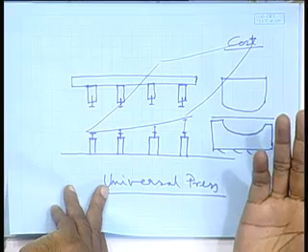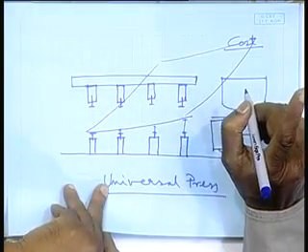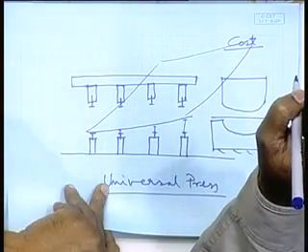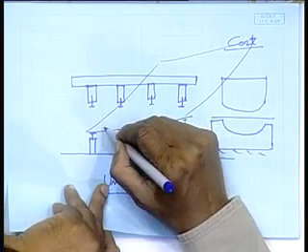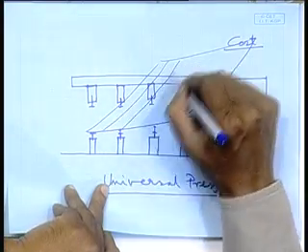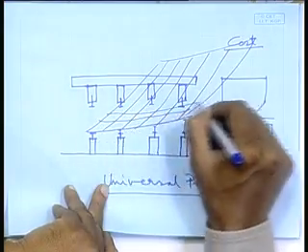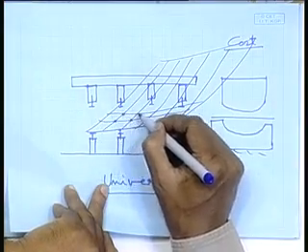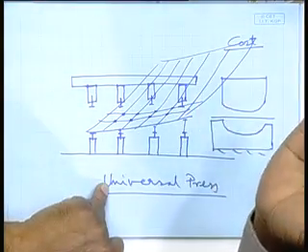So, again that same problem, how do you check it? And now it is a surface, it is not only one line. In case of frame, it was just that edge, it was a much easier thing. Now, the entire surface has to be checked. That means, essentially how do you check a surface? We will have to make a grid on the surface probably, right, and these coordinates are to be measured and checked with my required surface. Those coordinates are there, so I will have to check. So, how do we do this?